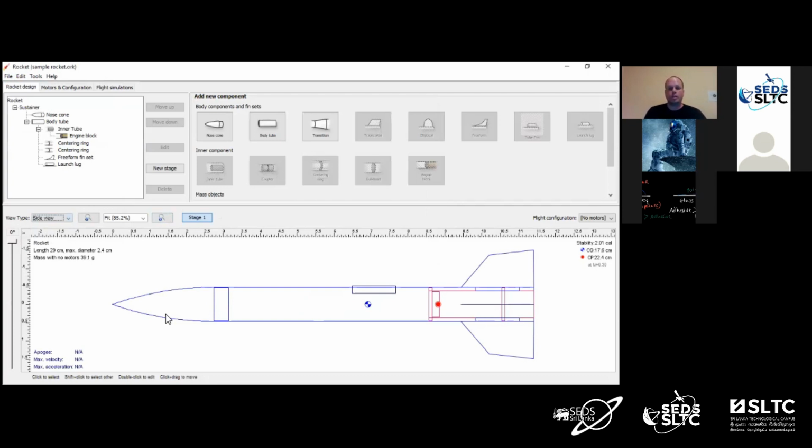So if you recall, we talked about a couple different recovery device types, parachutes, streamers. This is what a streamer looks like. This is fine for small rockets, you know, of this size, this very lightweight. It's really just a long piece of ribbon. This is like a piece of plastic ribbon. This is actually preferred to parachutes for small rockets because it's going to minimize the wind drift.